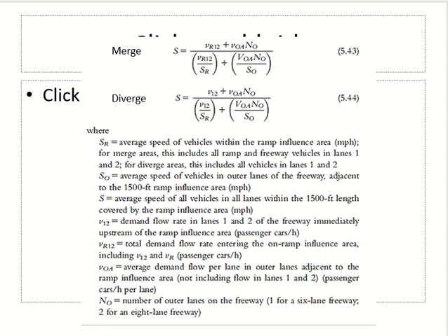No. They said it only works before level of service F. Okay, so that's why you stop. Okay, clear. We are just doing this for the sake of practice. In the exam or any other practical example, if you get level of service F proved by the capacity check, you stop there. That's it. Okay, clear.